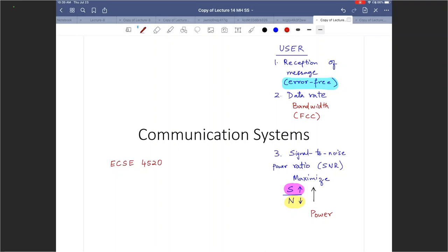And noise could come in through the channel, noise could come in through any sort of distortion. Even if you imagine a screw, right? That screw which connects 2 points, for example, can give you some noise. So noise is inbuilt to systems. Ideally, theoretically, you can say it can go to 0, but practically it can go very, very small, but it will not go to 0. And when you turn on, say, a spectrum analyzer, you can see that there is a noise floor, right? And that noise floor is essentially due to the thermal noise of the measuring device.